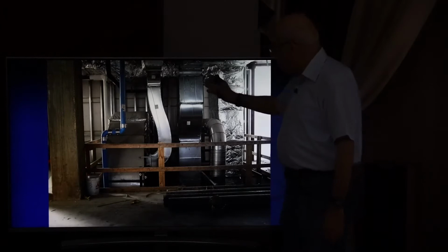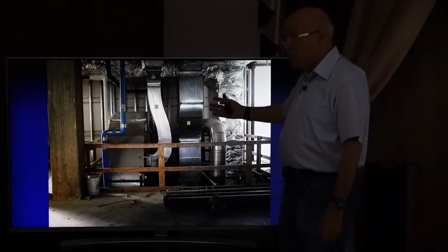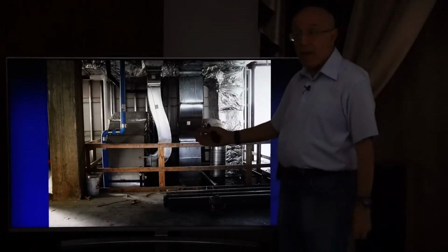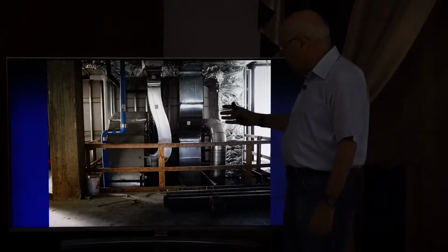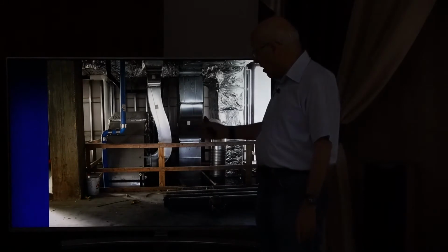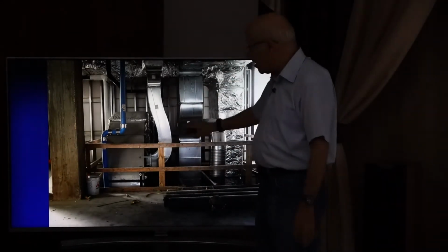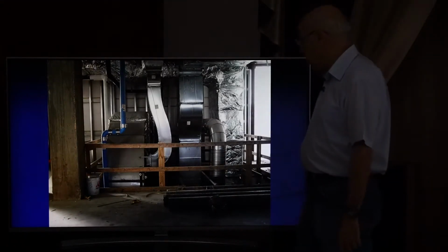This is something which falls on us as well as architects. This is a shaft. Now, this is a service shaft, and we put the air conditioning ducts and piping and sewage and water supply in these shafts, but we use them in a way that they allow for maintenance. Somebody should be able to go up and down the shaft to do maintenance, and this is a bad sample. It's overcrowded. They should have used a bigger shaft.